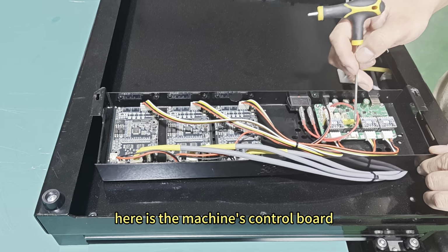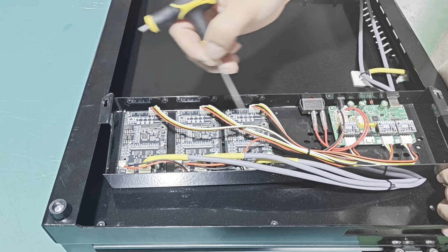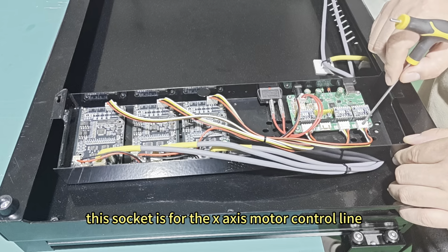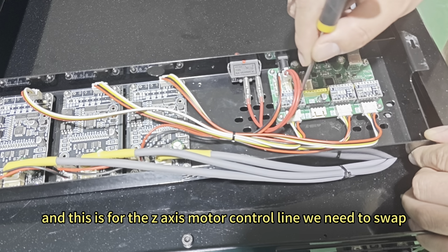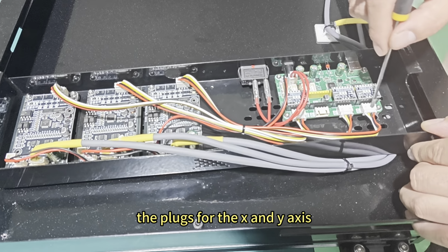Here is the machine's control board. Here is the motor driver. This socket is for the x-axis motor control line. This is for the y-axis motor control line, and this is for the z-axis motor control line. We need to swap the plugs for the x and y axis.